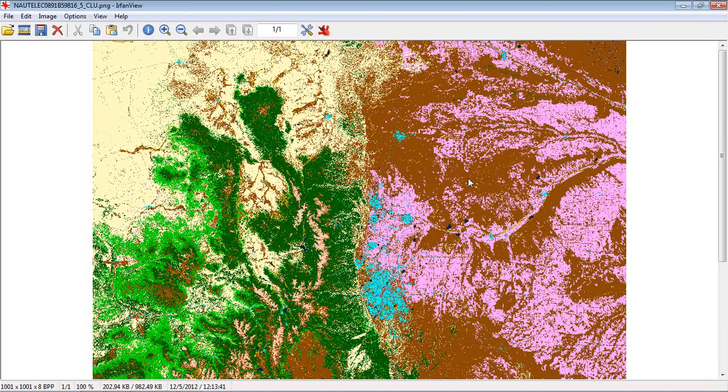If the radio beam goes through that land cover, you will have supplemental loss. In our case, don't forget that we were very high on the mountain. Yes. Our radio beam simply goes above the land cover and is not affected. That's right. There was no Fresnel zone encroachment in the land. For the land cover to interact with the path loss, it has to be within the first Fresnel zone. Yes. So as soon as there is clearance above the first Fresnel zone, there is no land cover loss added. Okay, very good. So the land cover loss defines what the program assumes will happen to the signal if it bounces off the earth.